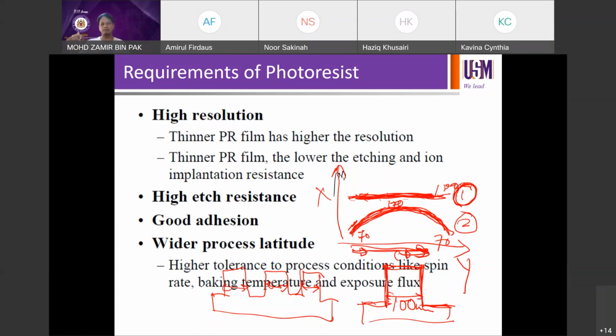The factors could be, the Y here could be dosage, focus, hot plate temperature, positioning of the robot arm, for example, developer flow rate, resist dispense flow rate, the spinning speed, cool plate. Thousands of different factors in the CD process could cause your CD to drift. And you want to know the process window, okay?